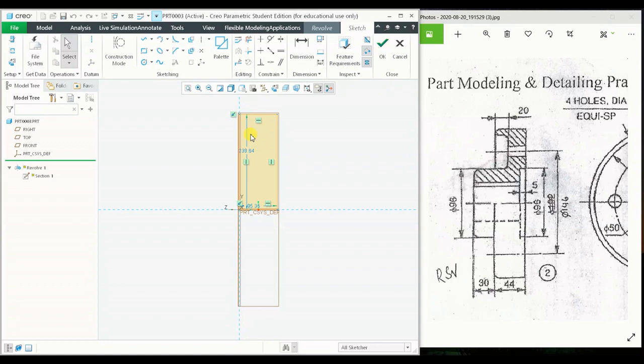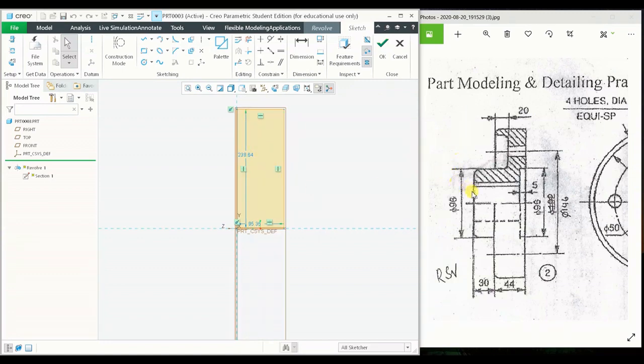Now coming to the sketching part of the geometry given to us. I will be going with the process of material removal. So what I will be doing is creating the total revolve block, a circular block which I will be assuming is the raw material. The dimensions of the block will be 30 plus 44. This will be the overall width, so I'll enter 30 plus 44. I want it to be a complete block, even though in the present sketch it is given as some different shape, which you can see with respect to the shaded region. I will be changing it.